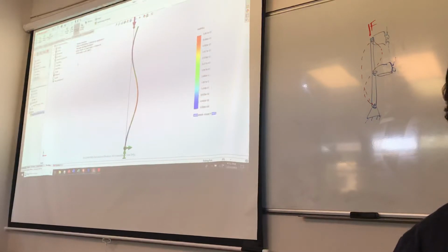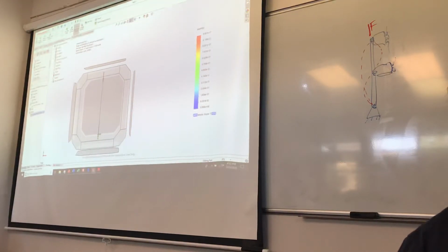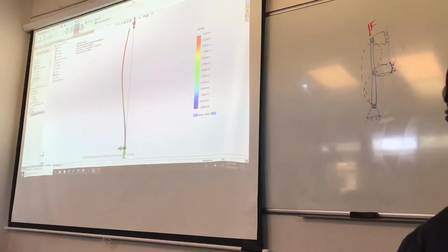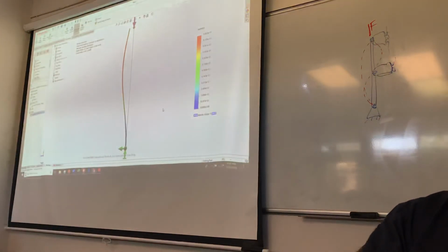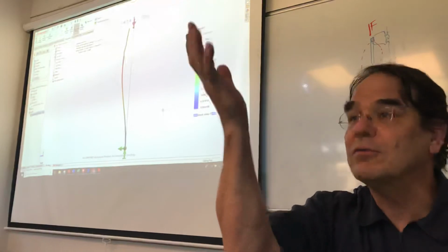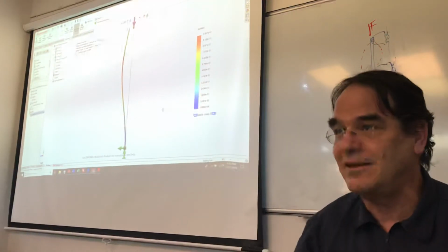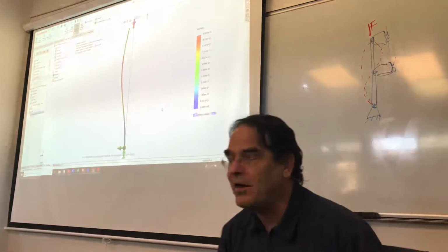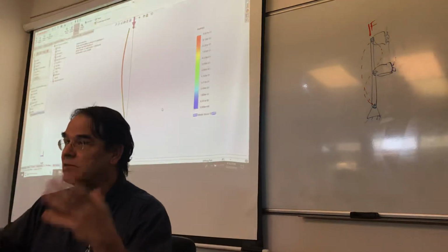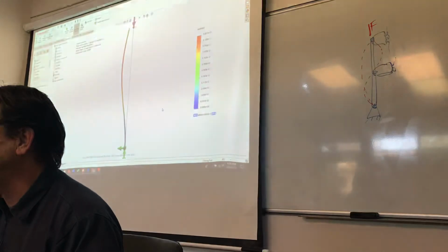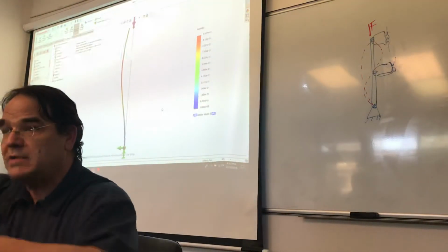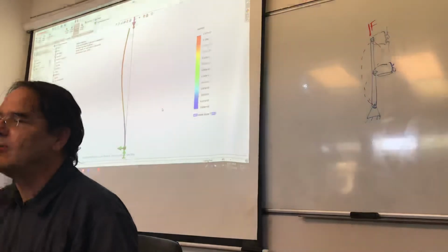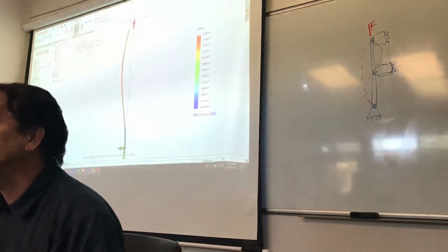There's the fourth one, right? It's almost at 30,000 pounds, right? And then there's a fifth one up there, which is probably in the other plane. Right, they go back and forth between the planes. There it is, and that's actually the thick direction, but it's a lower mode shape. It's because it's easier to bend it in the other one. I wanted to do this just to have an asymmetric cross section, so you can say these mode shapes are basically similar to each other, but they're happening at different values if the cross section's asymmetric.